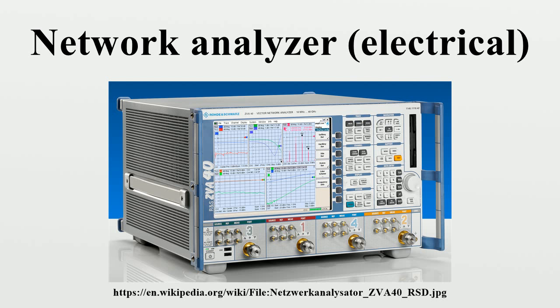and the vector network analyzer, which measures both amplitude and phase properties. A VNA is a form of RF network analyzer widely used for RF design applications. A VNA may also be called a gain phase meter or an automatic network analyzer. An SNA is functionally identical to a spectrum analyzer in combination with a tracking generator. Three prominent VNA manufacturers are Keysight, Anritsu, and Rohde and Schwarz.